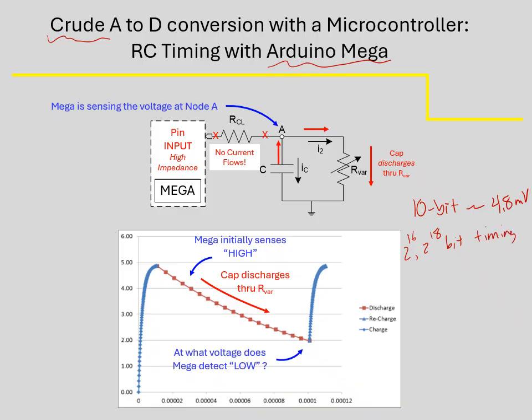So the Mega can measure the amount of time it takes for events to happen at much finer resolution than we can measure voltage output on the A to D converter. By using a timer to measure a change, we can measure every 15 microseconds. So depending on the circuit design, you might be able to measure a much finer voltage resolution.